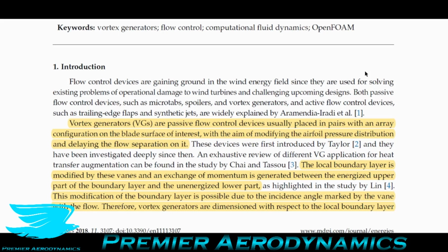So if you have 2 vortices rotating in opposite signs, when you're between 2 of them and they're both rotating such that they're pushing fluid down, the fluid in between them starts to get squashed and the boundary layer becomes much thinner. When you go between 2 vortices that are spinning in the opposite sign, but they're pushing the fluid up, then entraining the fluid and moving it up, the boundary layer gets much thicker. So those are for counter-rotating vortices.